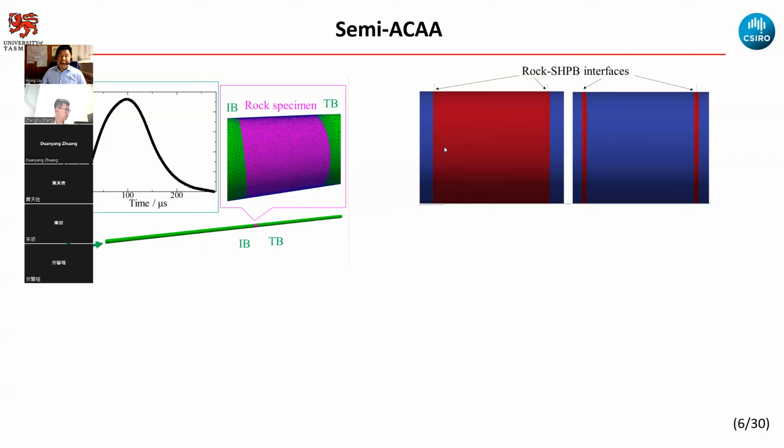So for the traditional FDEM modeling, as we know, before the failure, the cohesive elements are bonded together. So there is a transformation: before the cohesive element failure, what we use is the cohesive bond force. After that failure, what we use is the contact detection. So in that case, it involves a transition.